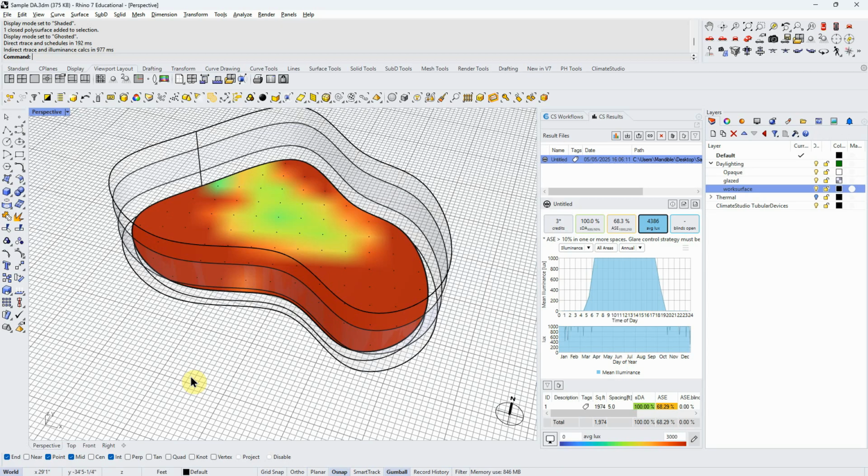If you're just in a pinch, 300 to 500 is a good range for a lot of different types of activities. But you should find specific targets, and if you're doing more than one space, you would have different target luxes for the different spaces. Okay, so anyway, 4,300 is really high and would not be something you would use in a place where you're trying to work, probably.